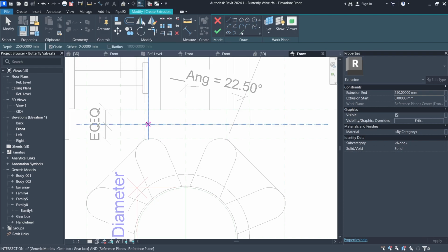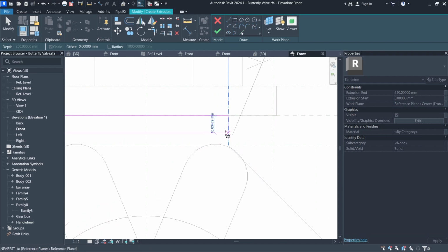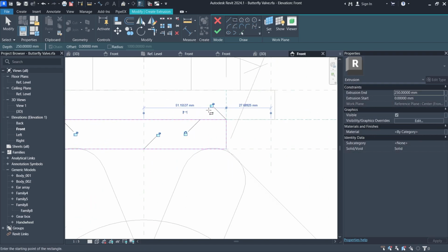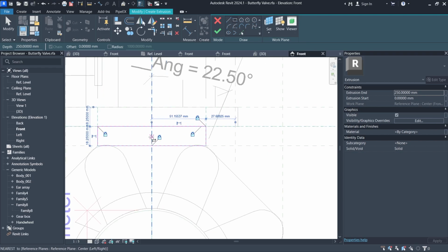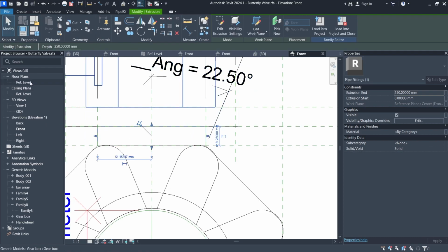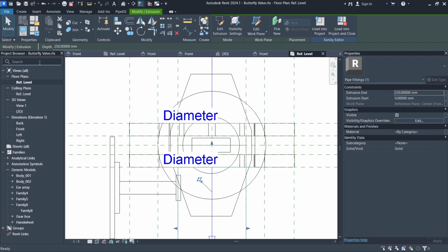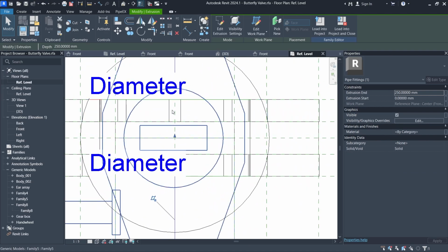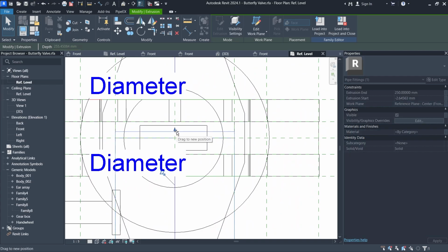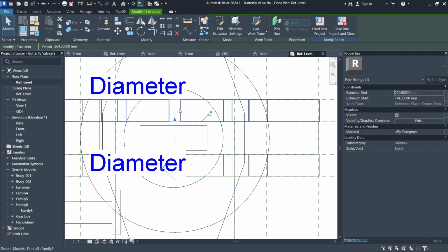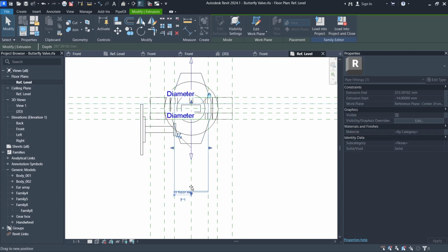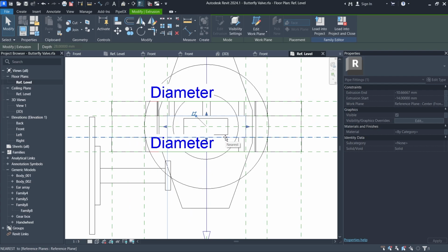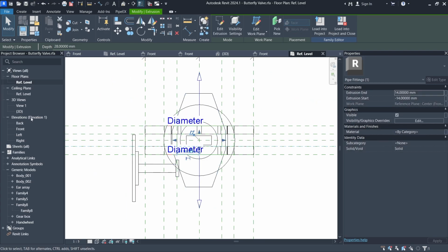And then I'll go to extrusion, and this time we will use this tool to create our next element. This one here. Close all the padlocks, click OK, and then we'll go to reference level view, and here I will adjust its position in the view. So we'll start over here and end somewhere over here, I would say.